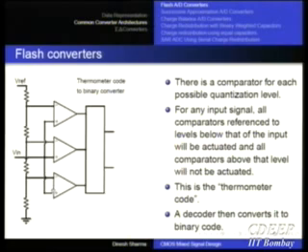So all the comparisons are occurring in parallel, and they do not depend on the result of comparison of the previous value of some more significant or less significant bit. So in short, drawing a parallel from arithmetic circuits, there is no rippling of carry or rippling effect in which something must be completed before the next bit can even be attempted. That makes the other system basically sequential. This system is basically parallel.